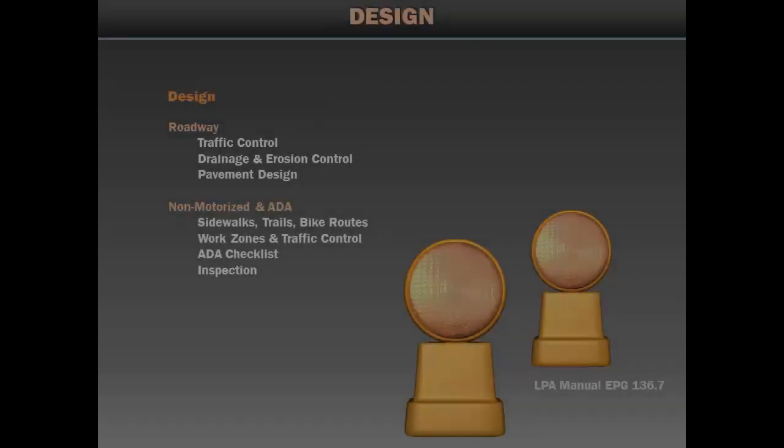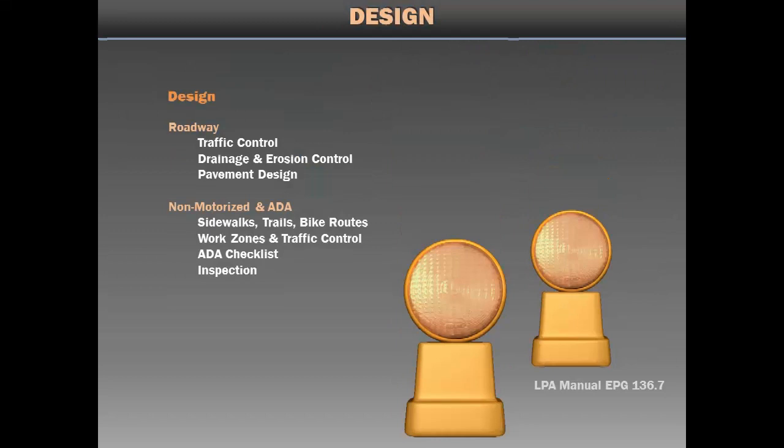Next, we will discuss drainage and erosion control requirements for your project. As discussed in the environmental section, all projects that have any excavation require a project-specific erosion control plan. The erosion control plan cannot be lump sum. If you have a rainy season, the erosion control plan may need to be changed to ensure water runoff is controlled properly, resulting in a change order. If the contractor is not reimbursed for the change, they will find other areas on the project to recoup their cost, resulting in increased construction administration.